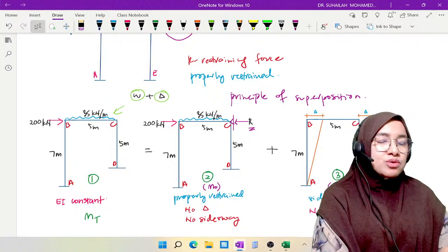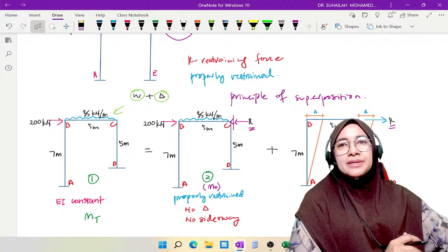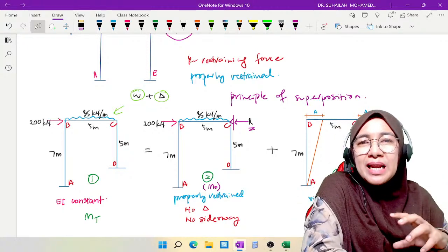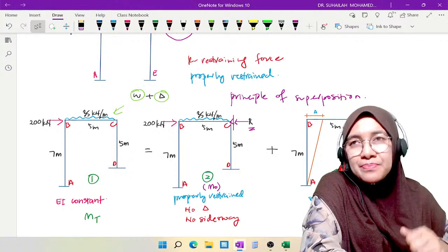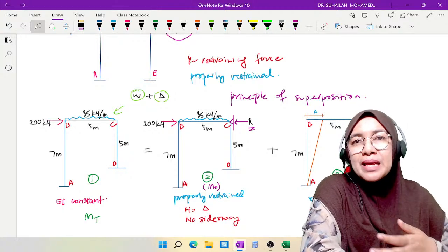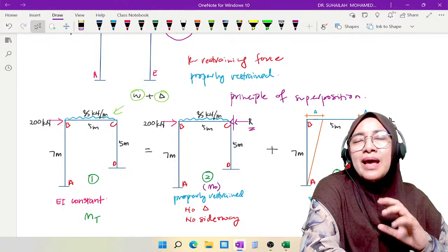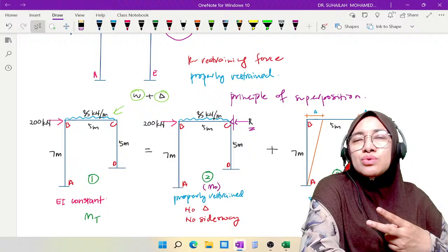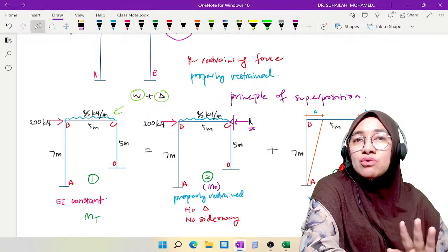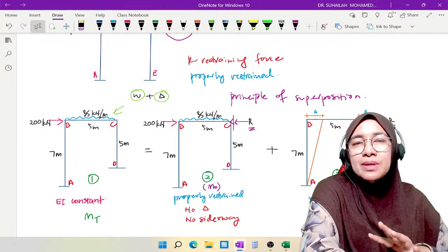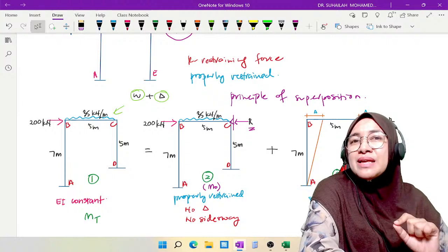side sway frame, as well as beam. But for side sway frame, this is very special because we analyze fixed end moment and member end moment, or internal moment, in the frame. We have to analyze by using two tables, table number 1 and table number 2. We cannot combine them, and the difference between the tables is only due to the FEM value.